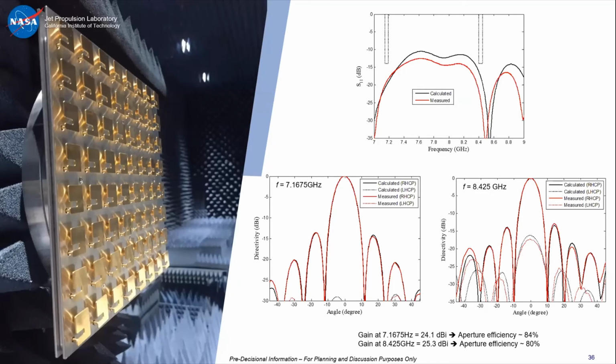To be able to fly on the surface of Mars, you need to generate much more lift. So the RPM of the blade is much higher compared to the typical helicopter that we use on the surface of Earth. As a result, the helicopter is limited in terms of mass. The constraint was 2 kilograms. So every subsystem delivered to the helicopter had very strict mass allocation, and it was non-negotiable. There was very limited margin allocated for each subsystem, and we knew that if we exceeded this 2 kilogram requirement, we would not be able to fly on the surface of Mars.